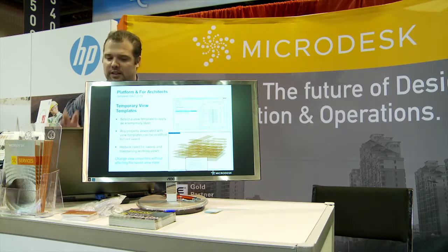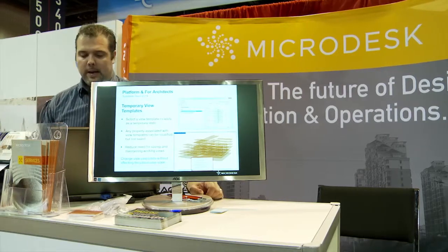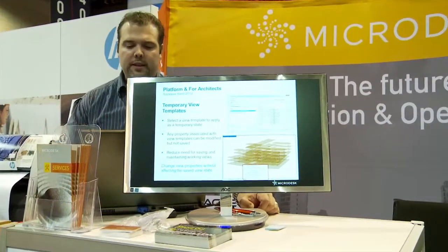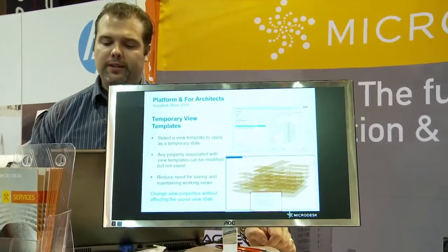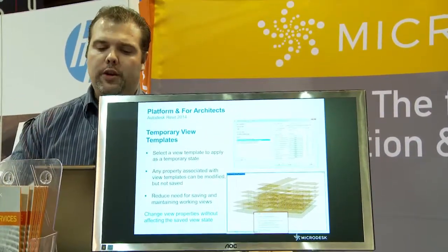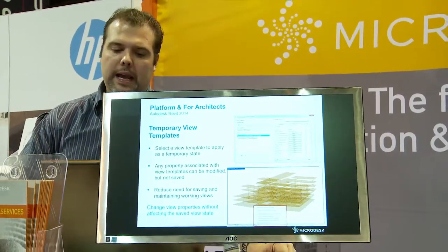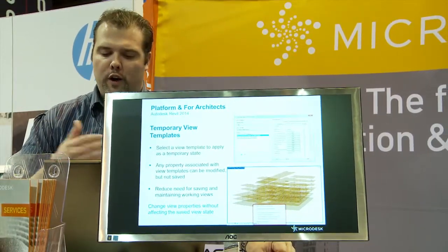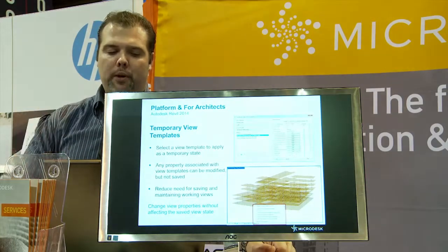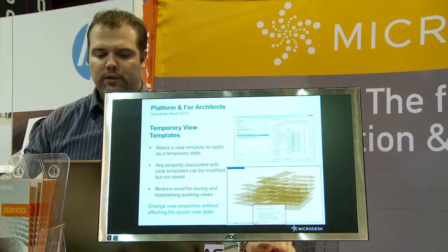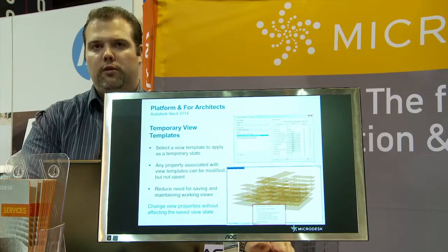So again, I'll just mention some of the relevant ones. This one is fantastic because of the amount of things that you can control in terms of graphics. You can create a view template, but it's a permanent thing that you apply and you can reapply again, and you can switch on and off, but now you can do temporary templates that you can apply to multiple views that do not affect the original view template.